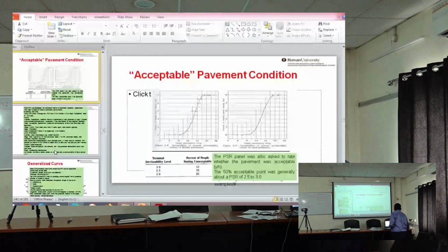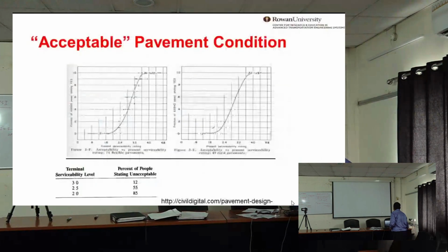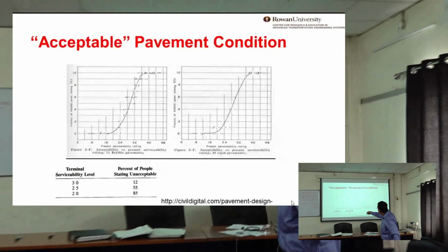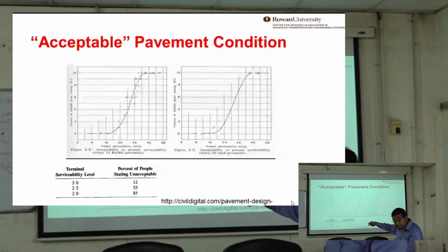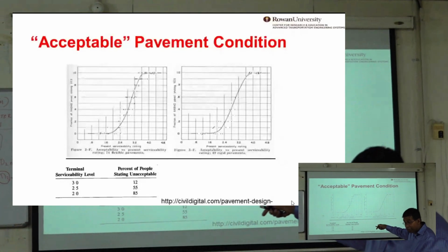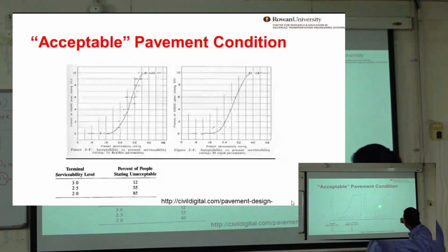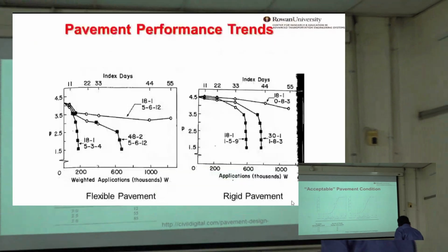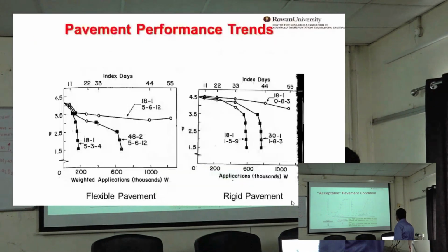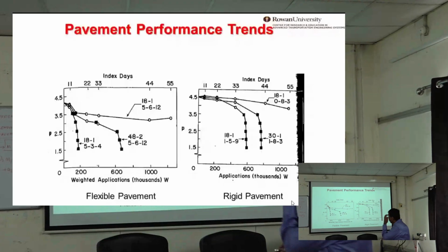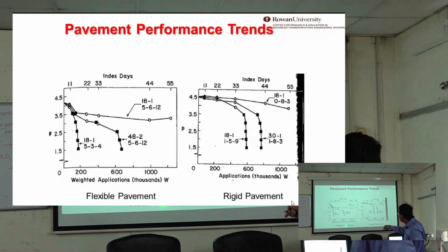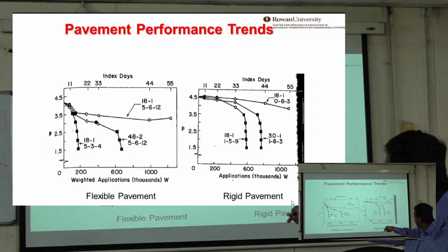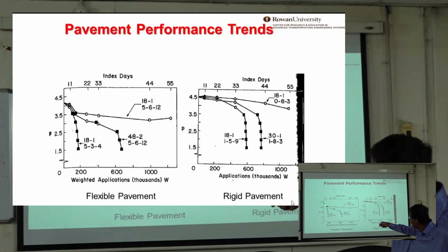This is very important. I just want to give you this example right here. Look at the data. This is from the AASHTO data. This is the tracking data. Very crude. They developed the model and equation just based on a very crude fit. You know what I mean? And then let me go down to the next layer. PSR, we will go to that right here. This is flexible pavement, right? And look at this, 18 kip single axle, and 5, 3, 4 are different axles. And look at the drop in serviceability index.